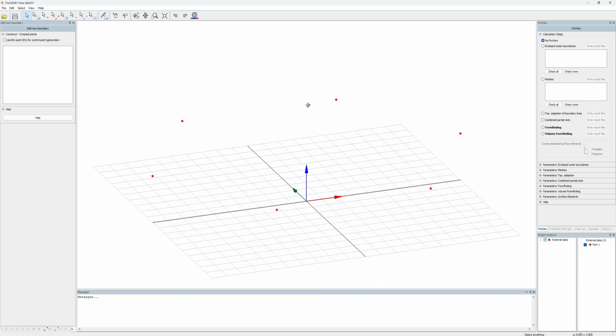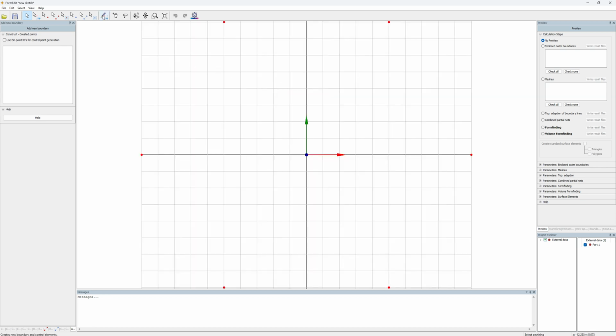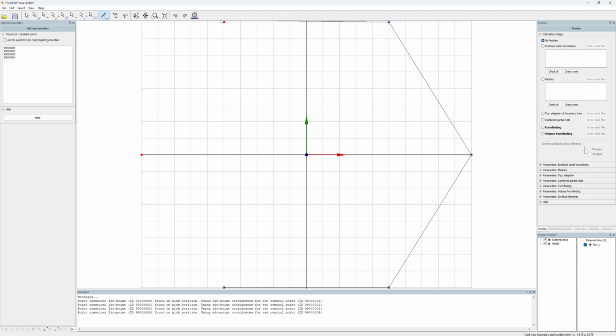In our example, they are located above the zero plane in the Z direction and already define the initial position and roof edge height. Using the pencil icon in the Quick Start toolbar, the boundary is created counterclockwise as usual. By clicking near the corner points, snapping is performed automatically, ensuring that the boundary points match the predefined coordinates exactly.